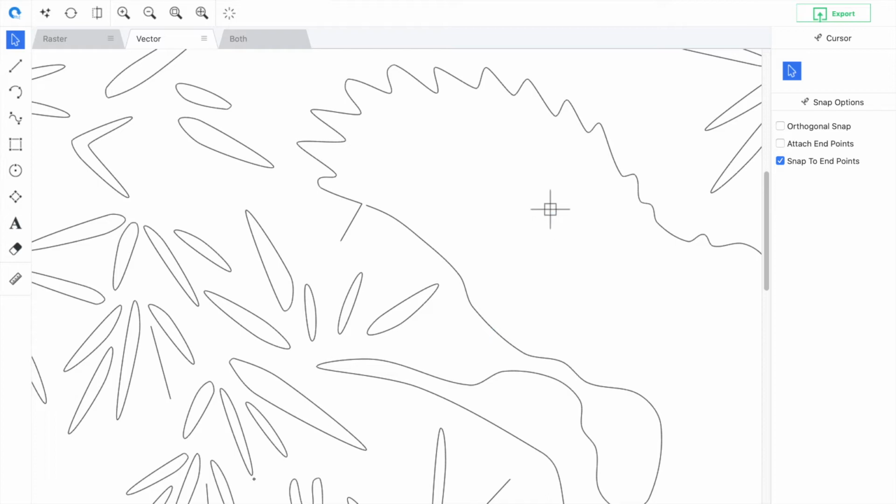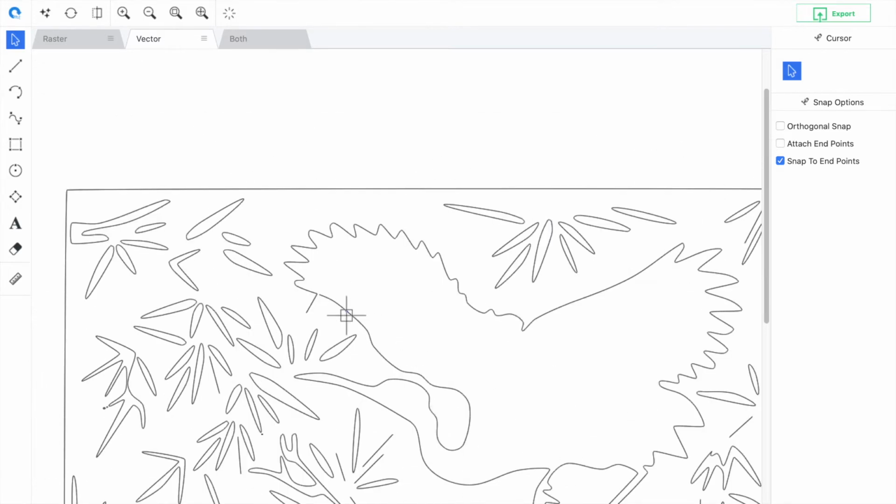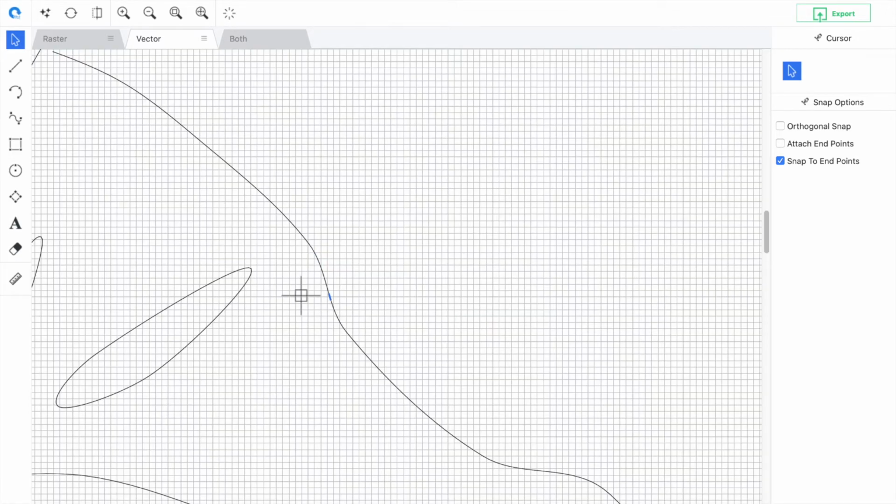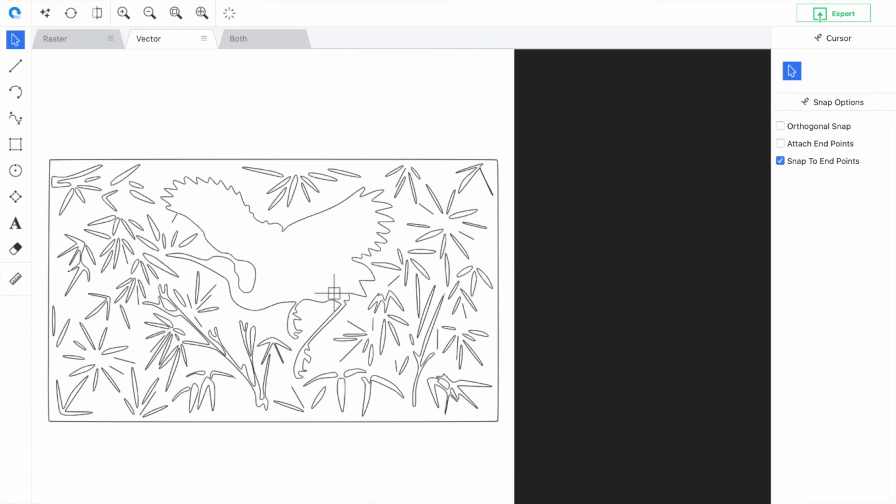One, your CNC machine is going to really struggle to follow all of these instructions, because what we're going to do is take this vector image, convert it to G-code or DXF, and that's effectively used as a cutting path by your CNC machine. So it knows that it's going to have to follow this bit to this bit to this bit to this bit, and so on, and it's a real struggle for your CNC machine.